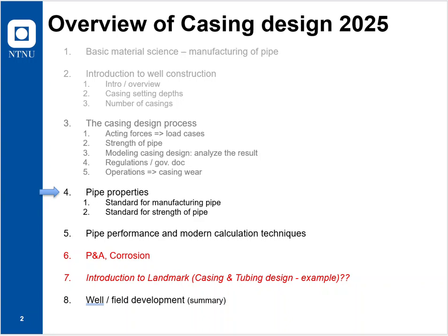Examples that I know in the Gulf of Mexico, really deep wells. If you're using the standard calculation software, you'll find that no standard casing will ever be okay. Whereas if you use the modern calculation techniques, where more or less all the hidden safety factors are removed, you see a different picture.